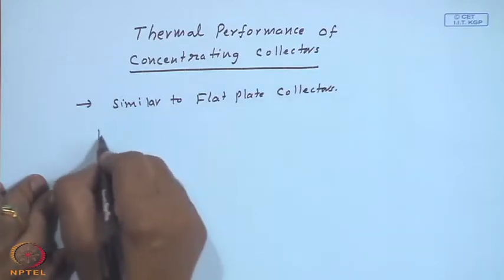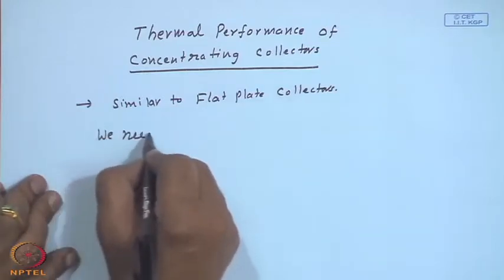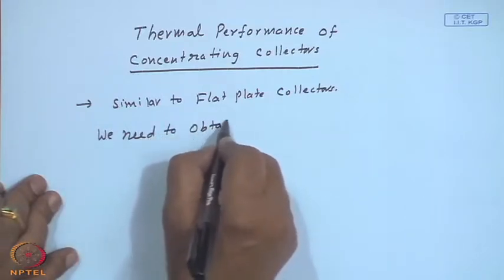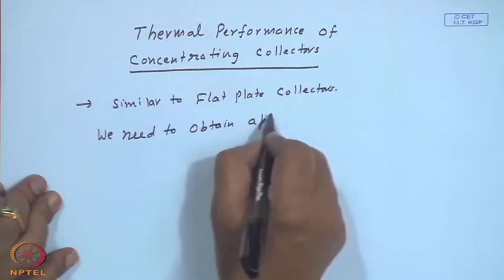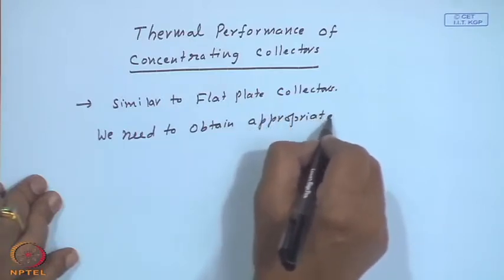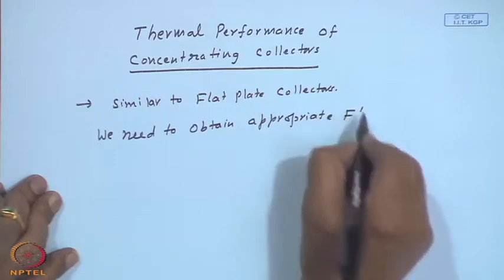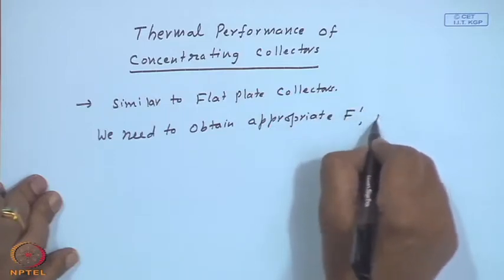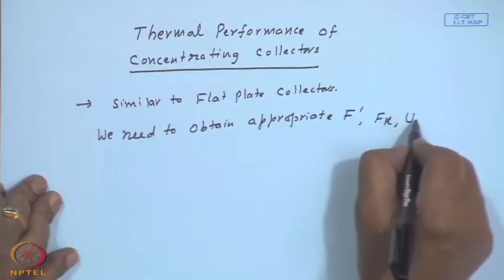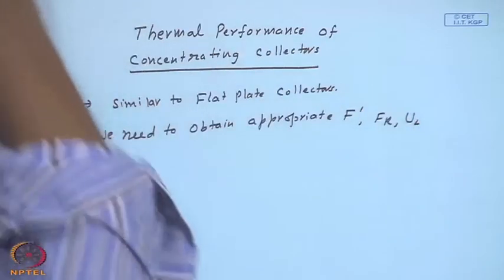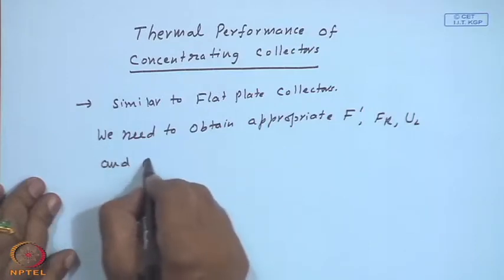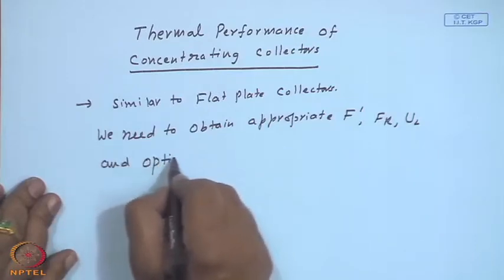And we need to obtain, however, appropriate F dash, the collector efficiency factor, F_R, the heat removal factor, and U_L, the overall loss coefficient, and optical parameters.